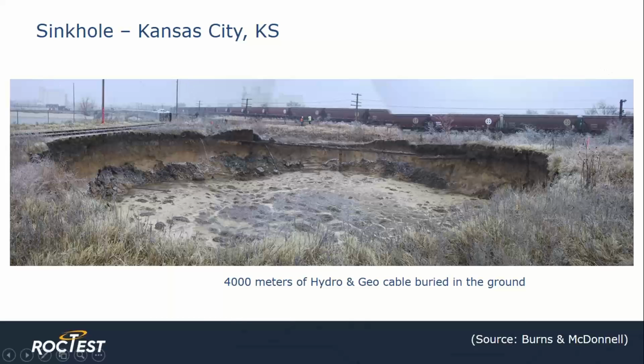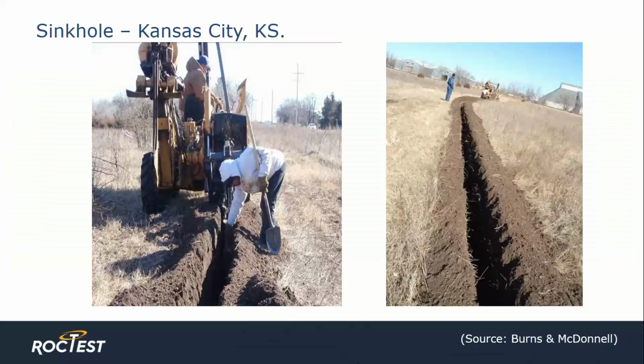The distributed fiber optic system was chosen to be an early warning system because it allows for simultaneous monitoring of thousands of data points using a single buried cable. This makes it possible to precisely locate and quantify the ground movement over the entire project. The detection cable was buried to a depth of approximately 4 feet in potential failure zones with an overall length of 2.5 miles.